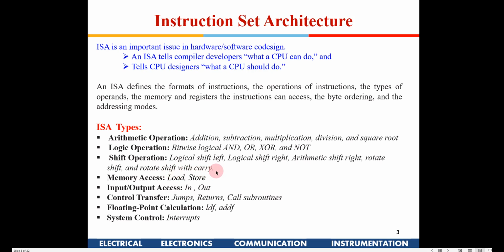Again, you could have rotate shift with carry also. Along with the register, the carry register also will be placed on the left-hand side of the register. Suppose it is an 8-bit register, the carry will become the 9th significant bit, and the entire thing will be shifted left or right as per rotate left with carry or rotate right with carry. You can give those kinds of instructions also.